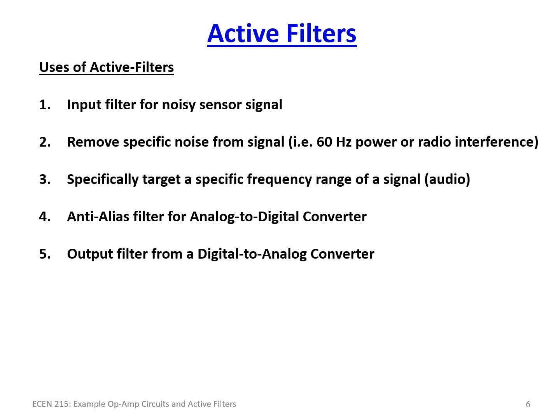And on the other side of this, you have a digital analog converter. Say I want to control something, make some computations, and then control an output voltage or an output current going to a valve, for instance, a proportional valve controller. Then you're going to want to also put a filter on the output to get rid of any high frequency noise that can come from those computations or anything that's happening in the circuit, because the output stage or control element is not going to respond as fast as you're updating it. So you're going to want to smooth that out.